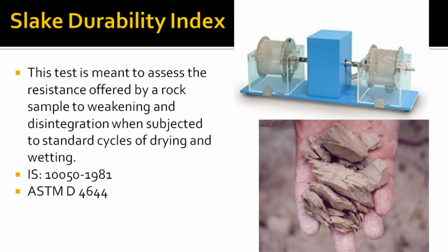So, if you're constructing a dam or if you're expecting your construction or your lithology to be submerged under water, then you should know its slake durability, which is the resistance against dissolution of cementing material in a rock.